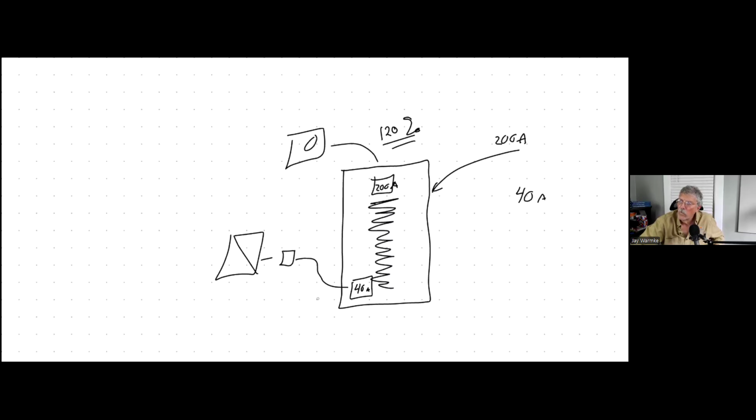So then the question is, what size inverter is that? If we're going to the maximum, what's the maximum size inverter? Well, we already have all the information we need to decide that. This is a residential system, so we know it's going to be working at 240 volts, and we know the amps, which is 40 amps. So what is the size of the inverter? Well, logically, watts equals amps times volts, so 240 volts times 40 amps. And we would get 4,800, is that right? Or 4,600?